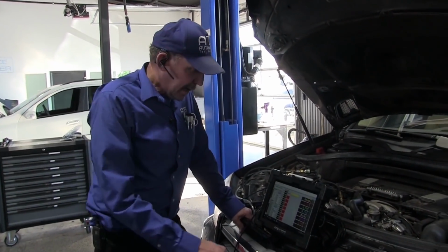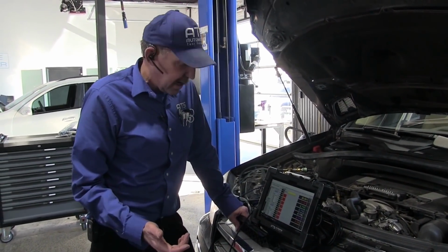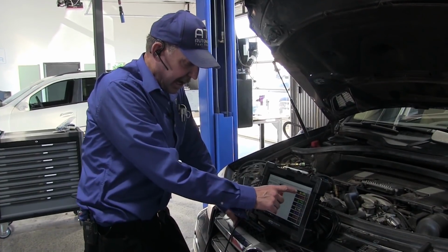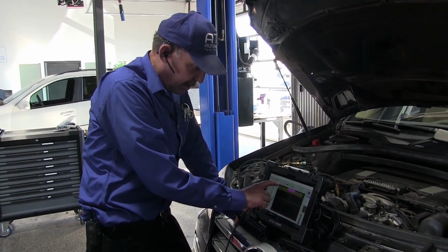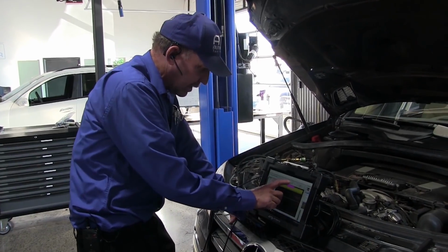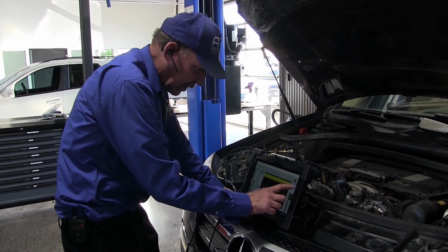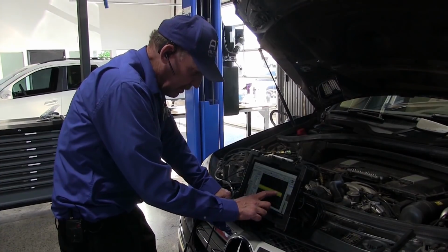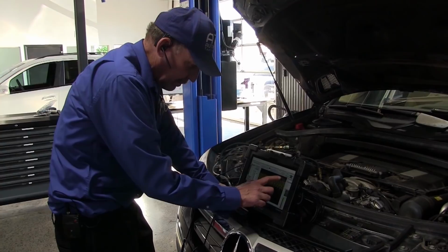Okay, so we're running, and we only got 36 pounds of fuel pressure. Now that's too low, guys. So we've already got a lack of fuel pressure. What I want to do now is go to where we're graphing. Oh wow, look at that, guys. That's cool. We have a problem. It's like the line's restricted, I think, but I'm not sure. But usually when you see this, it's an indication I've got a restriction.